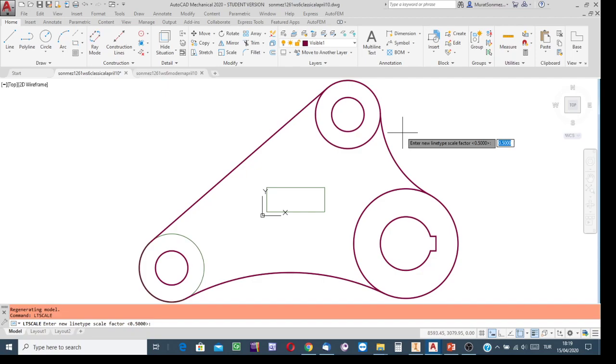If you increased the size of the projection 100 times, then to be able to see the dashes of the dashed lines in a suitable, reasonable order, write the same scale factor, because the new scale factor used while sizing the projection is not applied to the length of the dashes.